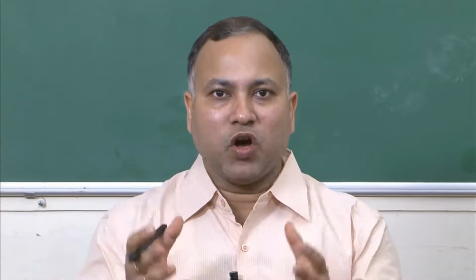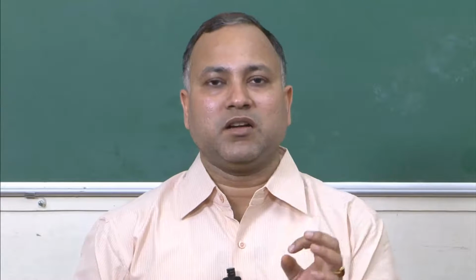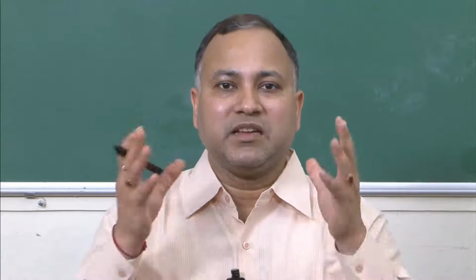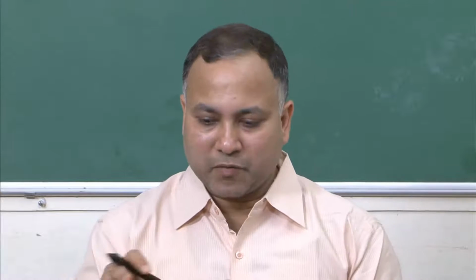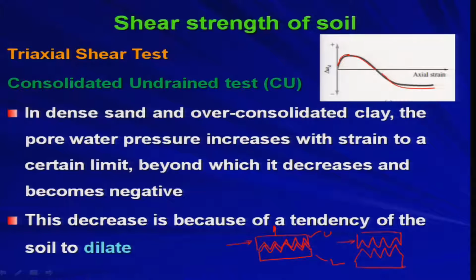Now, when you are allowing some expansion, some dilation, of course, you are attracting the water. That is how this dilation is happening, and this dilation will attract the water particles inside the soil matrix. And therefore, you will be getting some suction in the pore pressure, and that pore pressure will become negative. I hope that you have understood the phenomena. So, this is a very crude way as well as an easy way to understand the dilation.